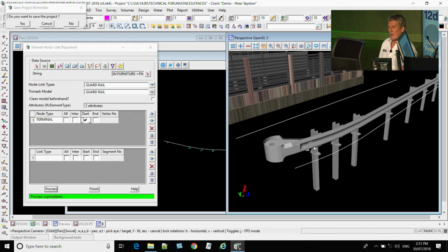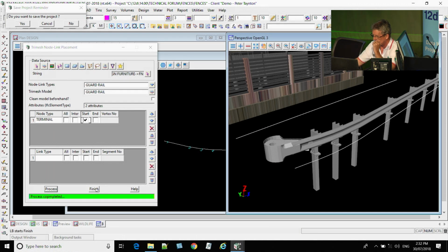But that's the idea. You can then go and position that 12DA file, and that's where I reckon a lot of things will happen, is with the 12DA file. So you position it where you want. Naught's where you expect the origin to be, and the orientation of it is where it's supposed to be, because it will actually look at the string that I picked and work out the perpendicular rotation for the 12DA file. So all you have to do is draw it yourself, or grab an OBJ from the internet, and then bring it to 12D, convert it to a Trimesh, and you've got some fancy looking thing that you can add to your fence and so forth. So that's how the place works.